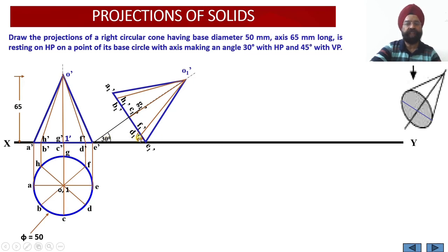Now this was not given to us, so I am going to take this out. Please check this. I am going to take this out, so this will be rubbed. Now there is no proof that I have tilted it with respect to base at an angle of 60 degree, right? This is only to facilitate one thing, that whenever I am shifting with respect to base, I am ensuring that my point or the corner or the edge will be planted onto the horizontal plane or on the XY line.